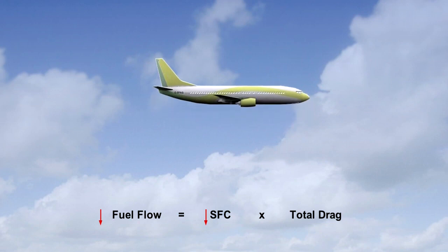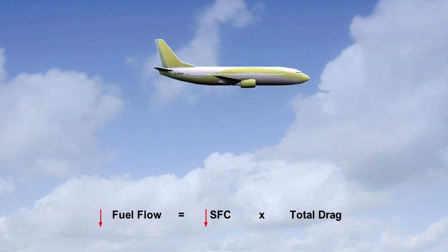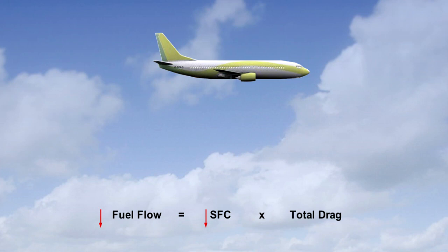Its effect, though, is a little complicated and is very dependent on engine type. Generally, jet aeroplanes become more efficient as altitude increases, partly due to the decreasing ambient temperature, but also because of the increasing RPM required to maintain thrust. Therefore, theoretically, the maximum endurance of a jet aeroplane will be achieved when flying at or above the tropopause, where the ambient air temperature is lowest.